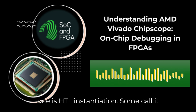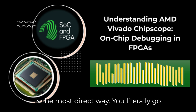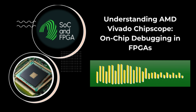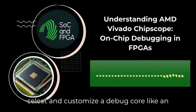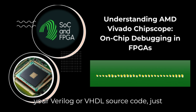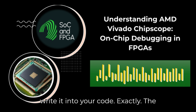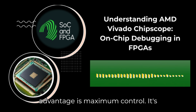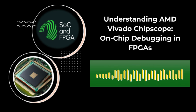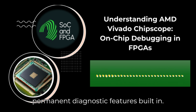Method 1 is RTL instantiation. Some call it IP plug-and-play or RTL insertion. This is the most direct way. You literally go into the Vivado IP catalog, select and customize a debug core like an ILA, and then instantiate it directly in your Verilog or VHDL source code, just like any other component. Okay, so you write it into your code. Exactly. The advantage is maximum control. It's explicit, it's visible in your source, it gets version controlled with your design, you know exactly which RTL signals you're probing, often preferred if you want permanent diagnostic features built in.